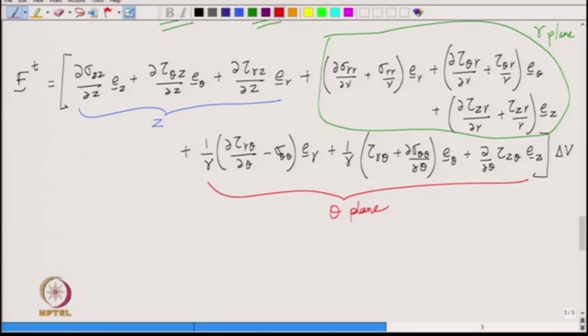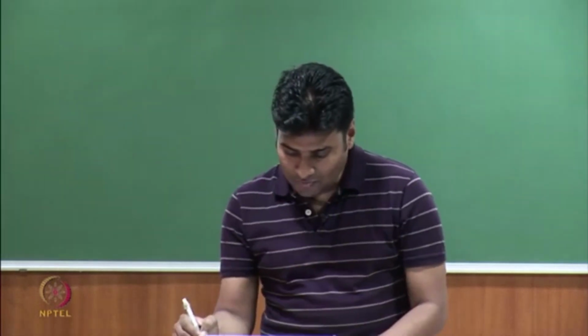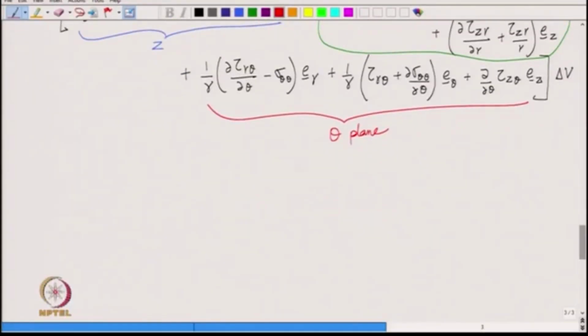You know, on the cylindrical element we will also have the body force, is not it? Okay. And the body force, can you recall from the Cartesian coordinate system, we simply have to find it at the center of the element multiplied with the volume of the element. Here also we can simply have the body force at the center of the cylindrical element multiplied with the volume plus the higher order in volume, small o of delta V.